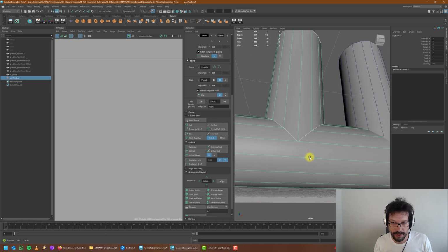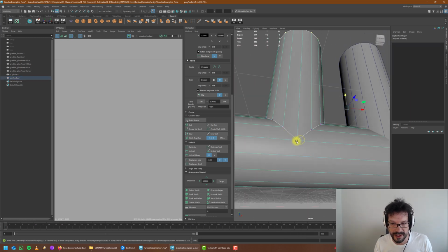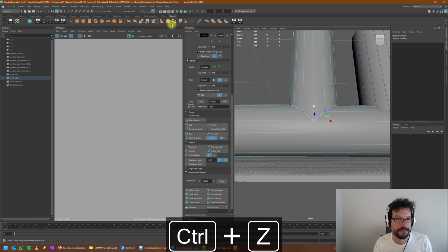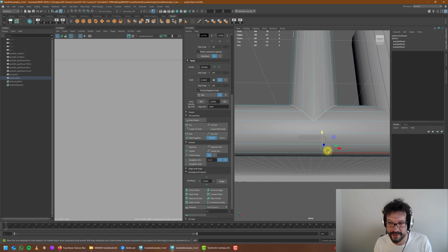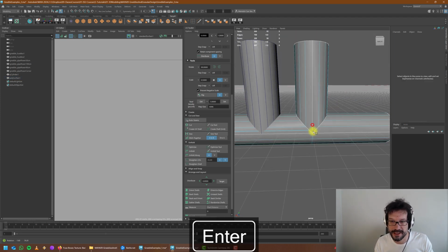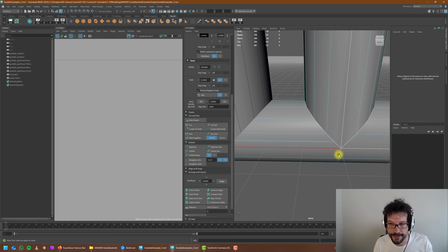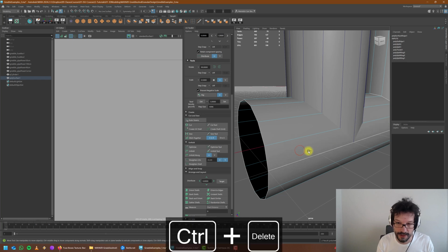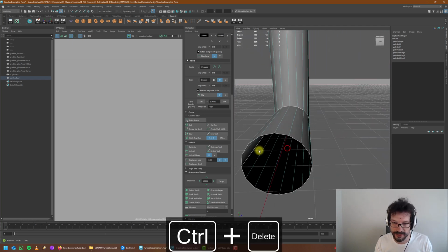Now obviously we have a fix to take care of here, because this vertex is creating a 5-sided polygon, an irregular pentagon, let's say, and I want to fix that. Okay, so I'm going to draw an edge right here, slide it here, and then basically connect it on both sides. Okay, apparently there's an edge issue here. Always check your work, so let's get rid of it by control deleting.